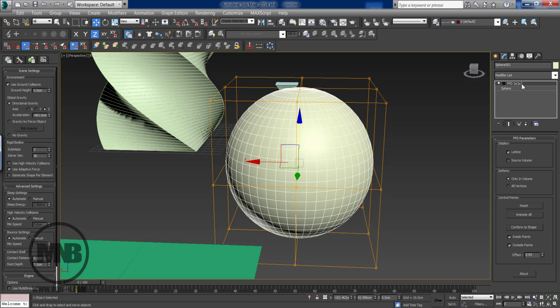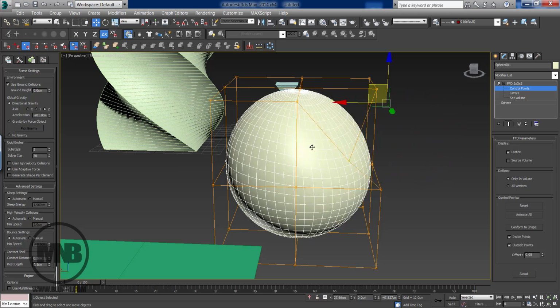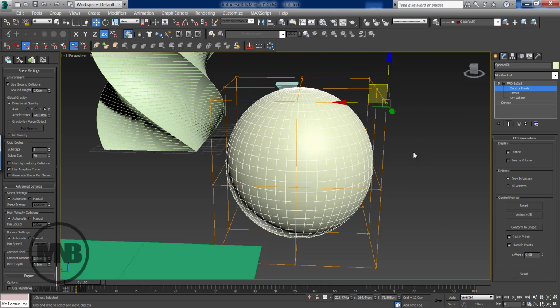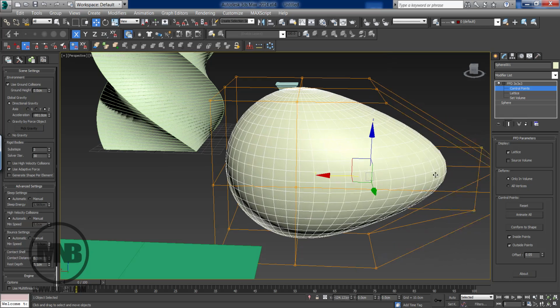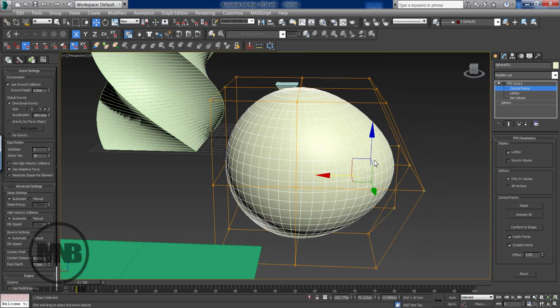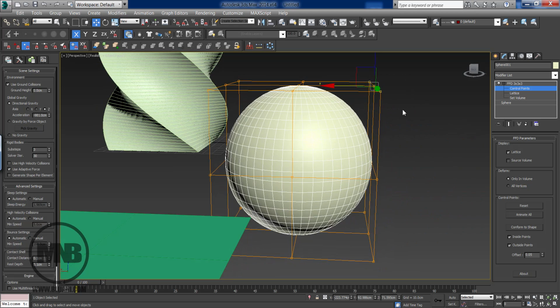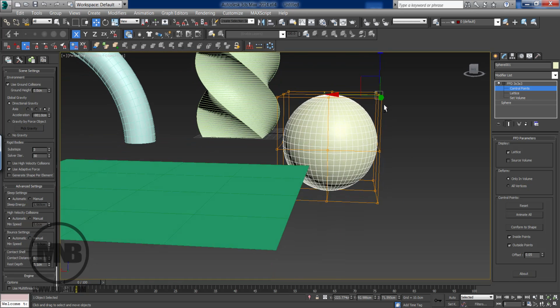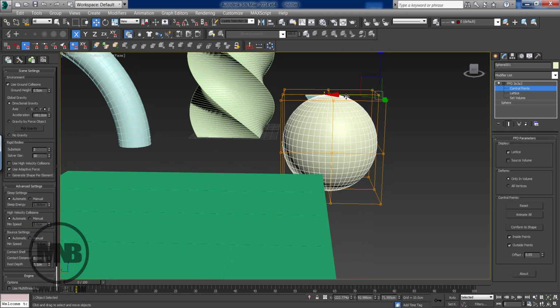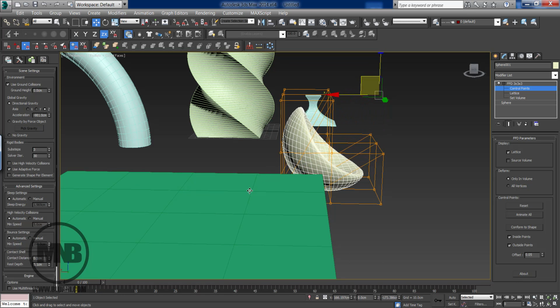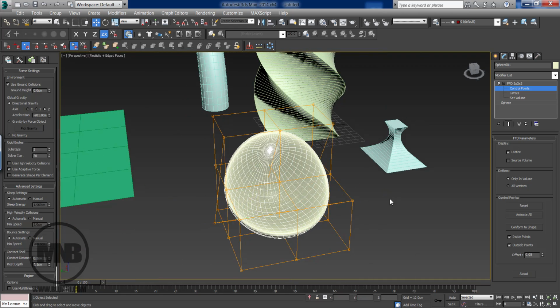So to access these points, all I have to do is just press on the FFD or press on the plus sign and select control points. Same thing, if I press in here, it will select the control points. Now I can select each point and I can do this kind of modification. So however I move these points, the object will move from the inside. So what I'm gonna do, I'm gonna select the top 3 control points. I'm gonna move them on the Z, X, these 2, and I'm gonna push them diagonally down. I can end up with kind of a chair.